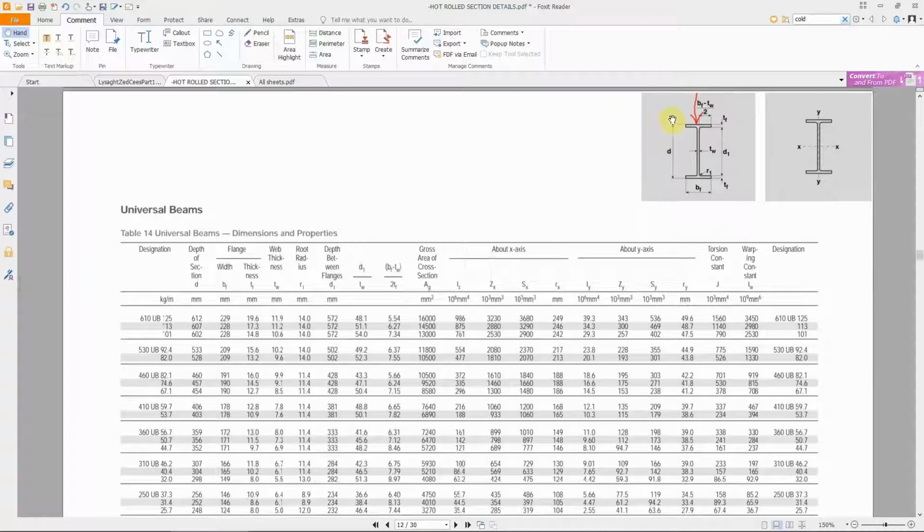As we agreed, the important size for us is the depth, how deep it is. That's 600, what we call nominal. Very important to learn this word. When we say nominal 600, that means it could be 607, 602, 612, around 610. This is what is referred to as nominal.